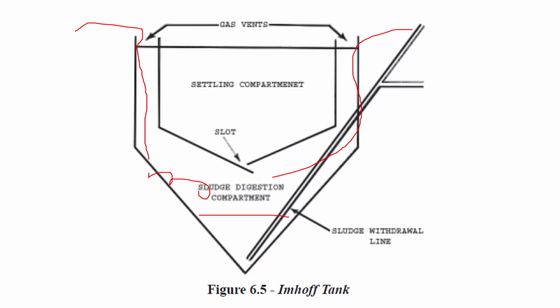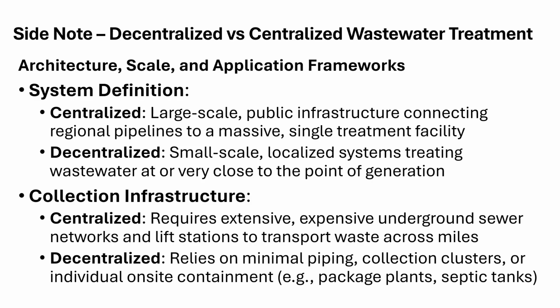Okay, they're just collected. And in here, let's use brown in here. This is where your wastewater is coming in. Okay, and your sludge builds up, comes down, and forms your sludge blanket here. And we can take that sludge away via these removal lines. Okay, hope I didn't confuse you too bad. Like I said, for a combined unit, you got a boot seal. For an Imhoff tank, you have these chambers off to the side. Sorry, I'm a little discombobulated today. Sorry about that.